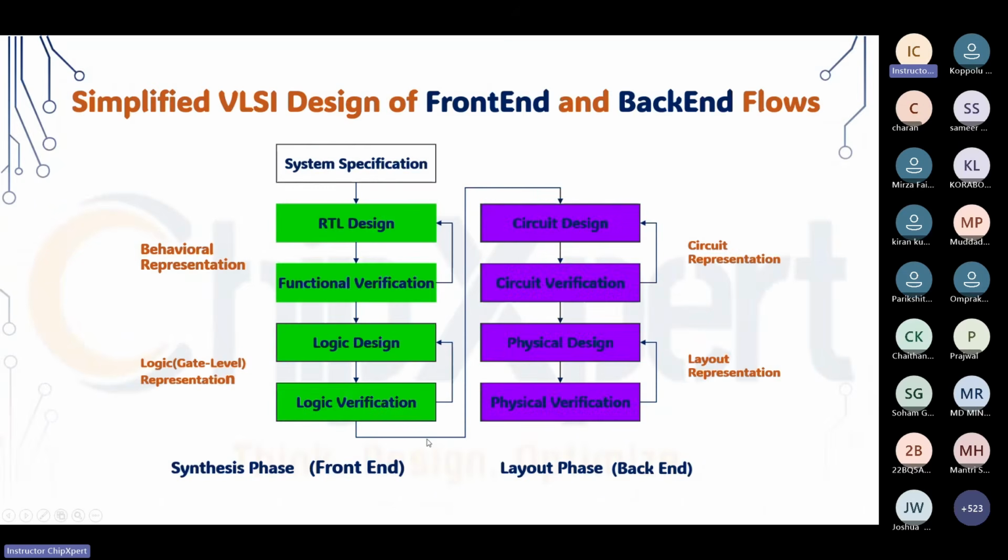Okay, so now understand this is the front end design, where the RTL design, functional verification, logic design, and logic verification will happen. In the back end, the layout, circuit design, layout verification, physical design, and physical verification, all these things will happen.